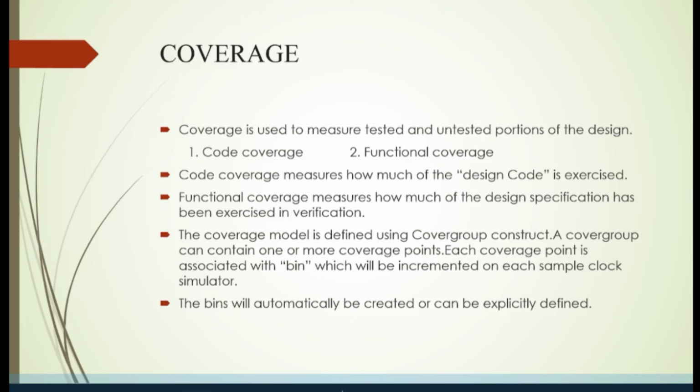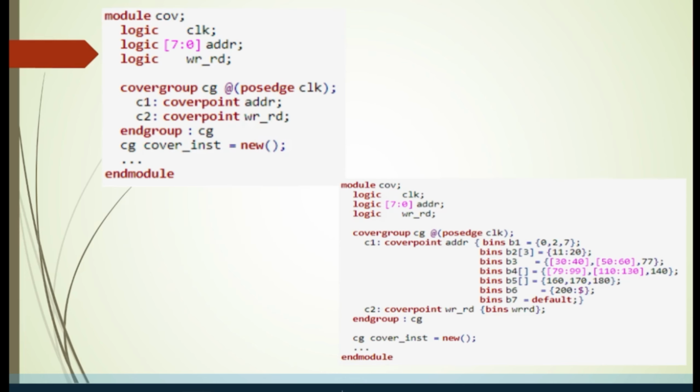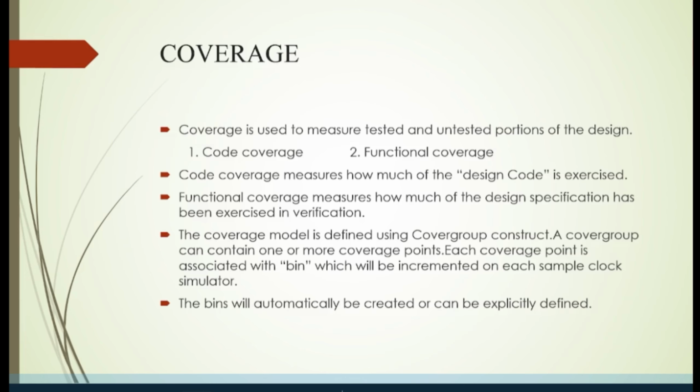You will have many scenarios. So code coverage or functional coverage will check whether all the scenario stimuli have gone to the DUT and whether the entire work is done properly or not. You will check it through coverage, right? These are the topics that you will mostly see in coverage.